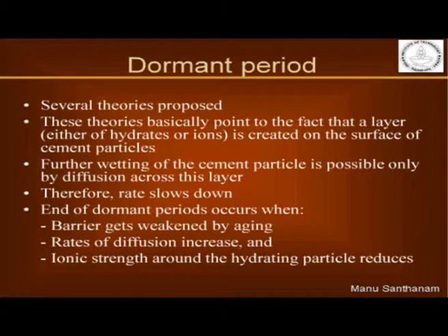So this dormant period is very crucial because the duration of this dormant period usually tells you the duration of the setting period, how long it actually takes for the cement to set. So it is very crucial from the point of view of application of the cement in concrete. And it happens because when you're mixing cement with water, you form this initial hydrate layer which sort of slows down the reaction. That is very crucial for us because we get the time required to actually work with the concrete. There are several theories that you can read in the slides on your own. It's not really something that we need to be concerned with, but the fact that it contributes to the overall performance of the concrete is what is important for us.